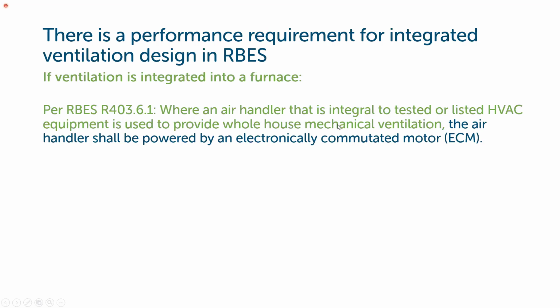But if you're using the ductwork of the heating or cooling system, then you're going to be relying on the blower motor of the heating and cooling system to move ventilation air most of the time. So code specifically calls out that the blower motor in your heating HVAC system needs to be an ECM motor also to be compliant with code. So there are these trickle-down implications, but certainly something to be aware of.